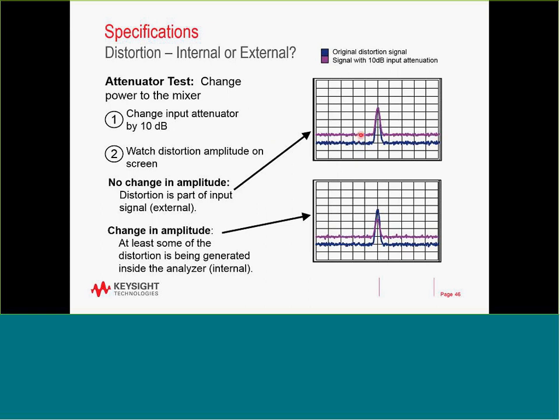The noise will go up. Your signal should stay at the same point if you increase attenuation. But if, when you increase attenuation, the noise goes up and your signal also goes up, it means that your analyzer was under compression.